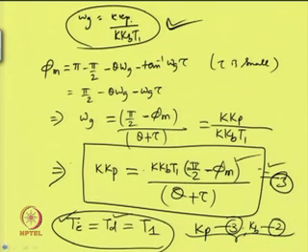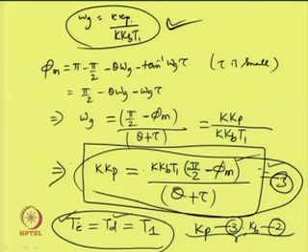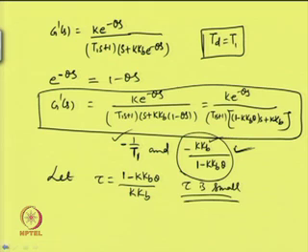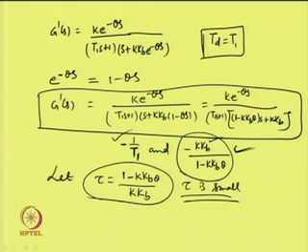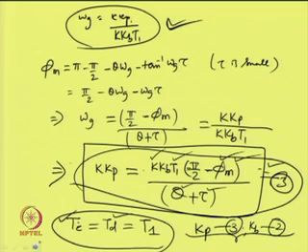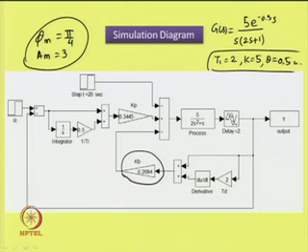Similarly, K P is estimated using expression 3. So, upon substitution of K, T 1, phase margin, which is nothing but pi upon 4, theta 0.5 and tau, expression for the tau is given over here. So, we have assumed the tau to be of this form. So, substituting all those values in 3, we get K P as 0.3445.